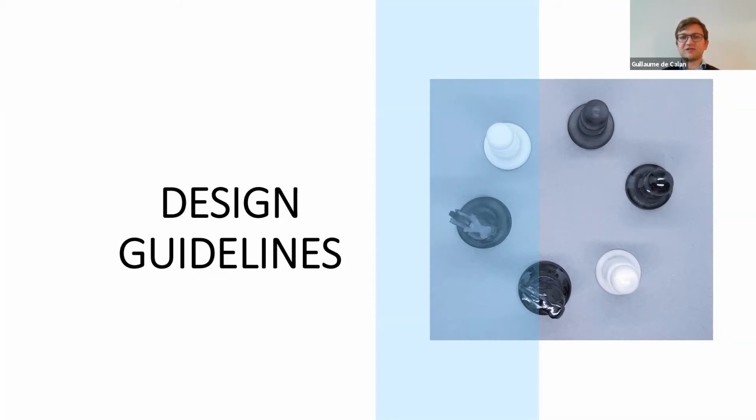It's just that when you get outside of these figures we will give you, you get to something more experimental, and you can't be sure before you print and you sinter the part that the result will be good. These design guidelines are here to help you design parts that will come out of the printer good on the first trial. That's really the idea.